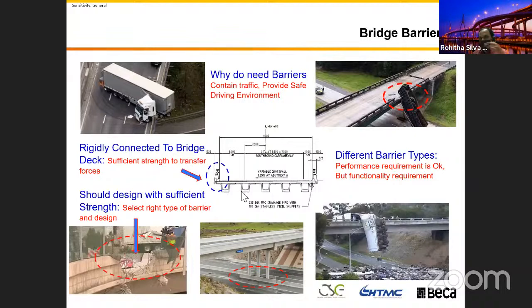Another thing, it needs to follow the bridge after you build it. You can't get an exact shape, because the bridge girders, pre-stressed girders, you know that one, creep, shrinkage, they have cambers, and then you can't have a uniform deck surface, but you have to overcome all these things when you are building the bridge barriers. That's what I said, it's very difficult to build. With my own experience, it's really time consuming. Most of the bridge projects, they get delayed. There are some reasons they delay the bridge project, but most of the time it is because of the barrier construction.